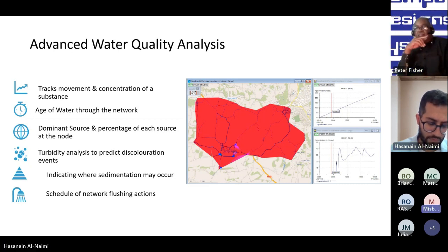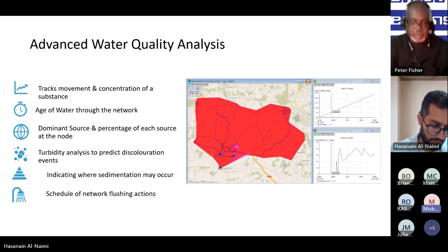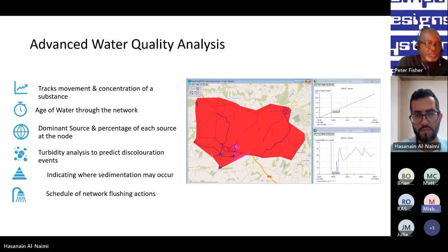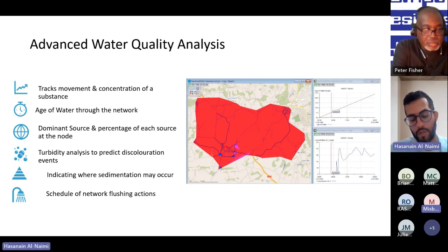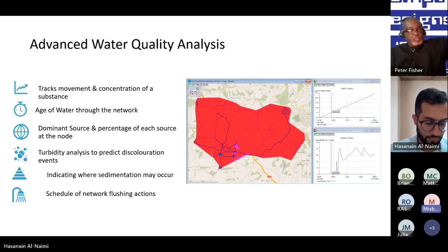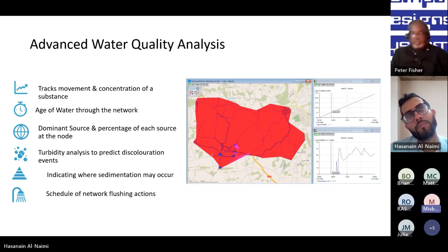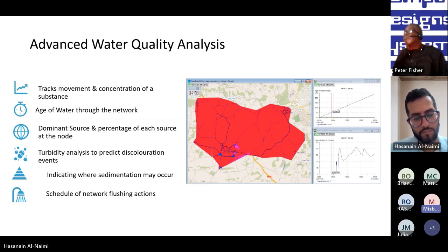When you do calibration, it gives you an insight of what the roughness friction factor of the pipe has become after so many years of usage. If you had data that you can use to do the calibration, you can put that data in the software, and then it can simulate and come up with a range of roughness coefficients based on the simulation runs.